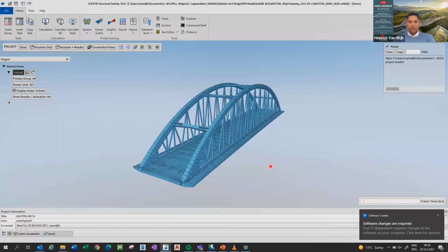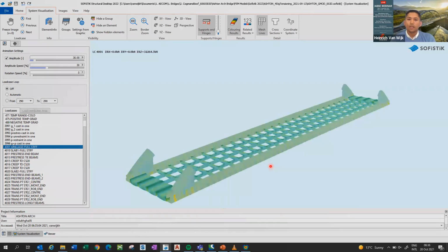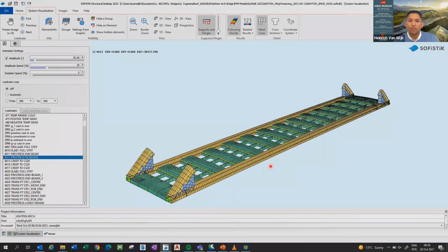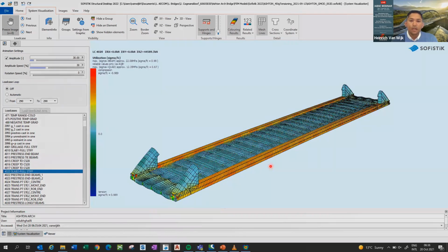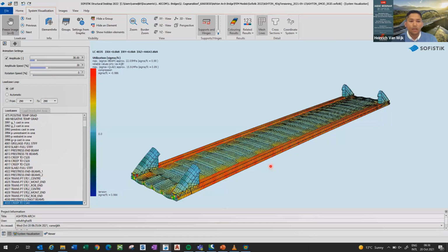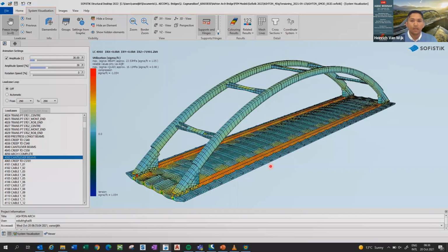So with the construction stages, prior to post-tensioning the longitudinal beams, we cast alternating slabs, as you'll see in the next construction stage. That was done so that the post-tensioning would flow into the beams as opposed to being diverted into the slab. And then we tensioned the end beams for bursting, and then the transverse beams, and then the internal beams, cantilever beams, and then the arch ribs.